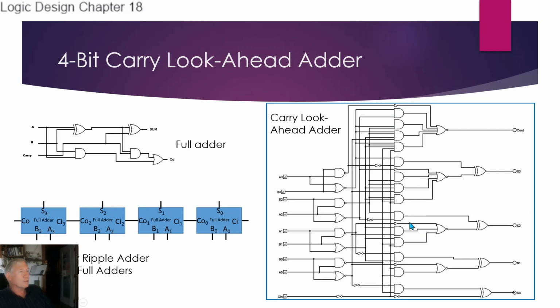So we still have, worst case, maybe 3 or 4 gates here, plus if we daisy chain them, maybe 6 gates or even 12 gates, but it's nothing like 128 gates, if, say, we did a 128-bit adder. So we do a compromise, and usually we can come up with a good engineering solution to make that work. Okay.